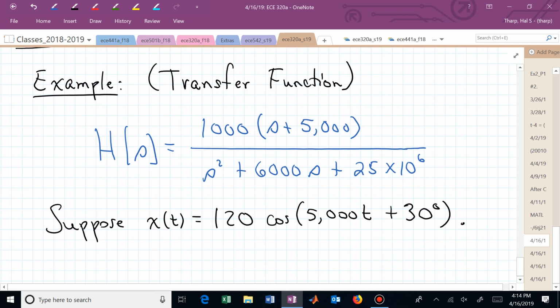In this case, where were we going? We wanted to check where the x's associated with H(s) are. Where are the poles? And here's a time-saving step. If you had a sixth order denominator and somebody had graciously factored it into 3 quadratic polynomials that were multiplied together, and they said, is this system stable?